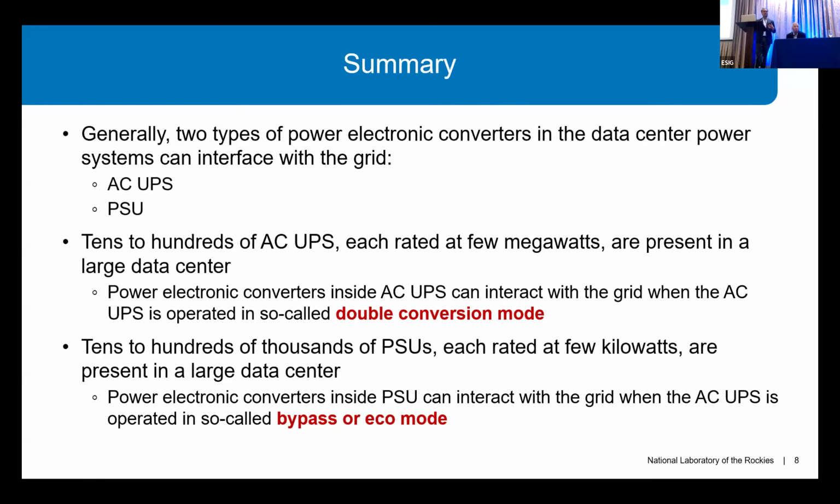So there is a lot of know-how within the industry on how to model these inverters for IBRs. In fact, modern medium voltage UPS with long duration energy storage use the same PCS or inverter products that are used in battery energy storage plants. So modeling of AC UPS is something that power system engineers are well versed in because of our experience with IBRs.